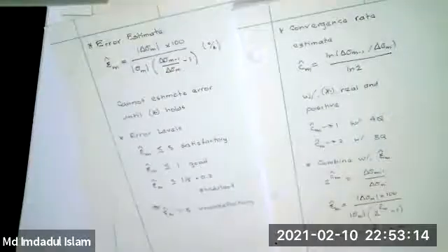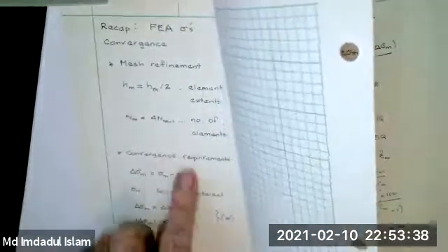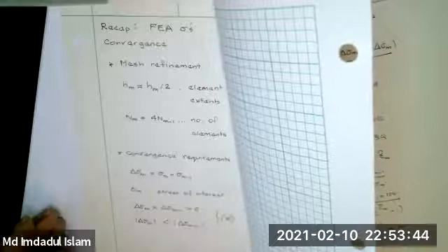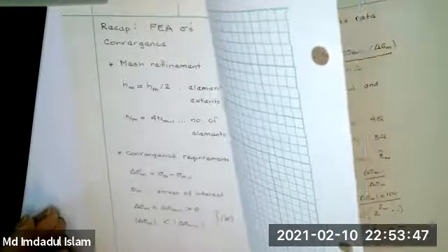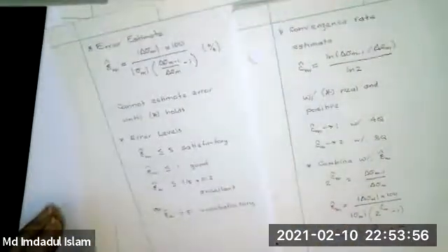That's a very fair question. You've calculated these stress points, and you could just say convergence requirements met for mesh, and give which meshes they're met for. You don't have to write this out. If you can see it, just looking at it, you can say convergence requirements are satisfied for M equals, and give what meshes you're talking about. It may not be all the meshes. You can just look at them, but you don't have to write this down explicitly. Any other questions?